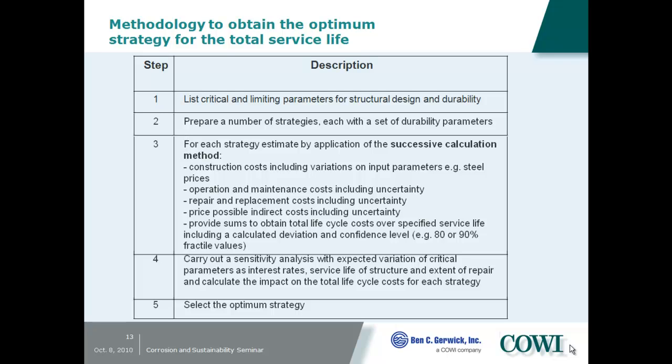What we then do in relation to life cycle cost is that we price all of the components that go into this strategy, also including variations and uncertainties, and also throughout the service life looking at what are the operation and maintenance costs during the service life, repair and replacements, if any. Also indirect costs, for instance, if you plan on or have a strategy where you have to hold up traffic at some stage, that is also a cost for society. Holding people, preventing them from getting to work, for instance.